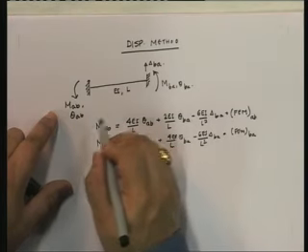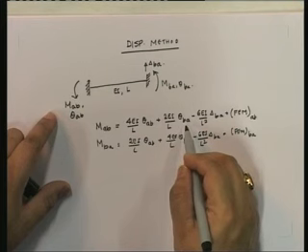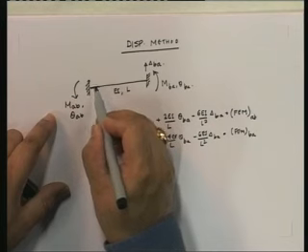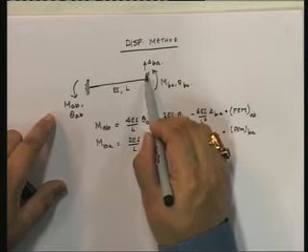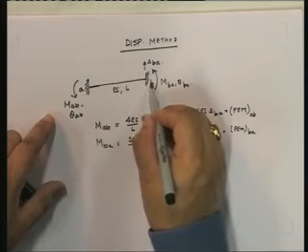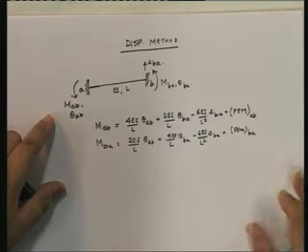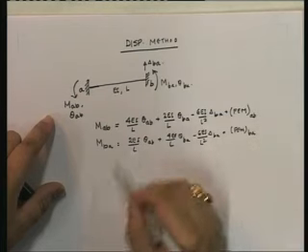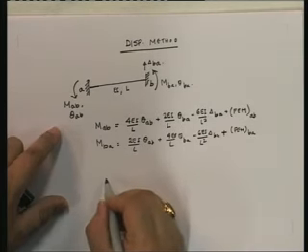This is where theta AB and theta BA are the rotations of the tangent from the original undisplaced tangent to the displaced tangent, and delta BA is the deflection of B relative to A, upwards of B relative to A. Theta AB and theta BA are positive anticlockwise, and fixed end moments and moments are positive anticlockwise. So this is the original definition.